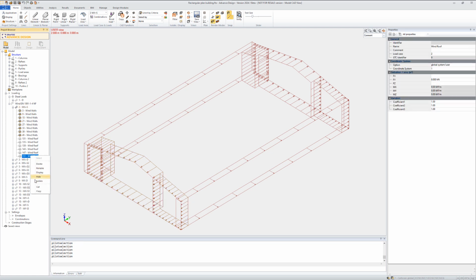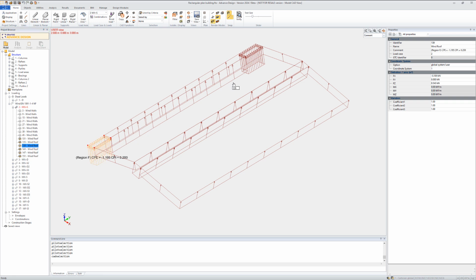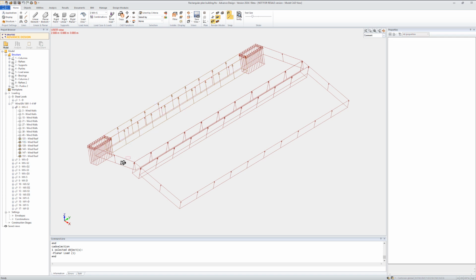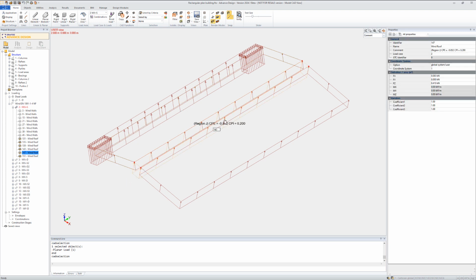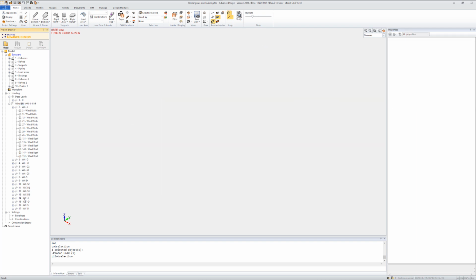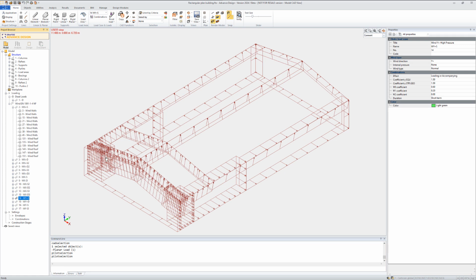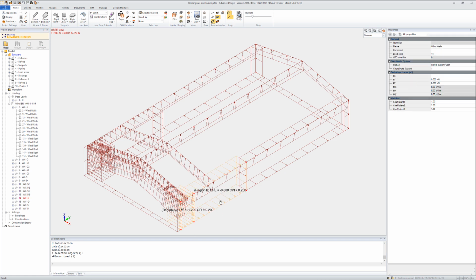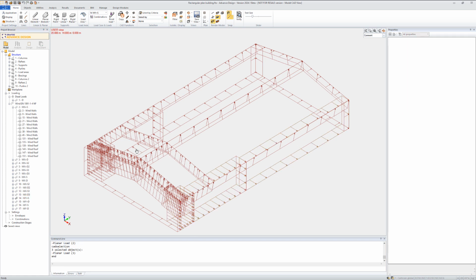And if we check the roof, you will find the peak forces in the corner. You've got the long G zone there. So here, every time you select a load, you can check the pressure coefficient and the naming of the zone. Here we've got a large H, the very long J, and finally the I with a small pressure coefficient. So this is for a lateral wind, and we can also check a front or back wind, where we've got the edge effects there. And then the A, B, C zones will be parallel to the wind. So pretty straightforward.